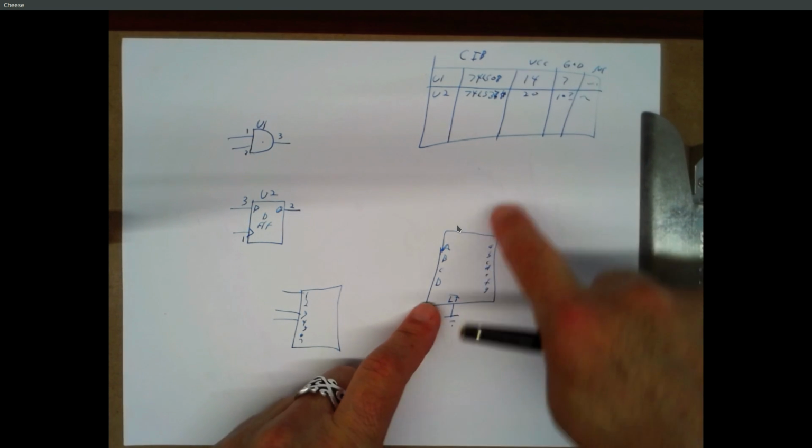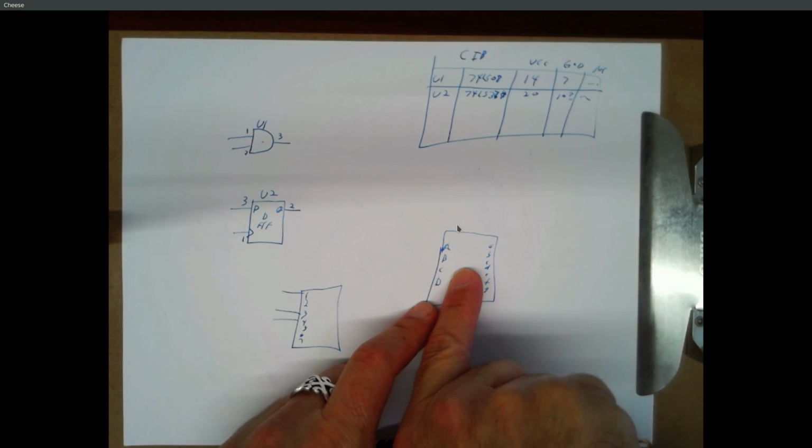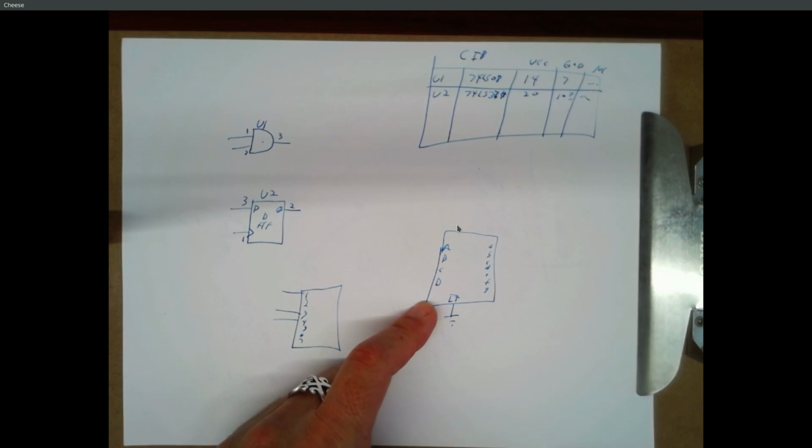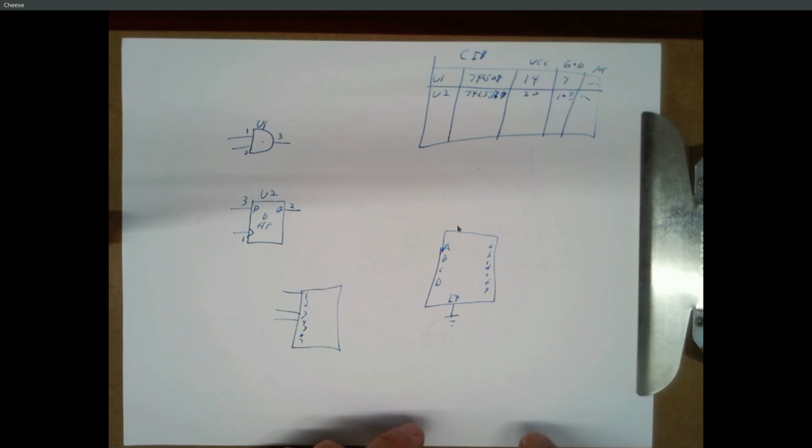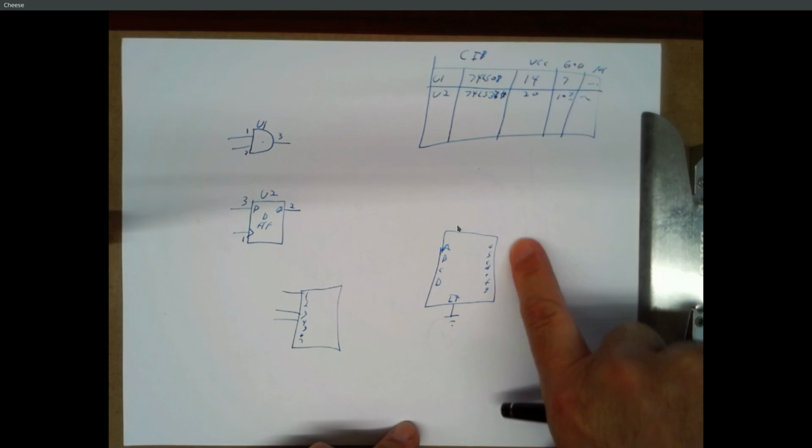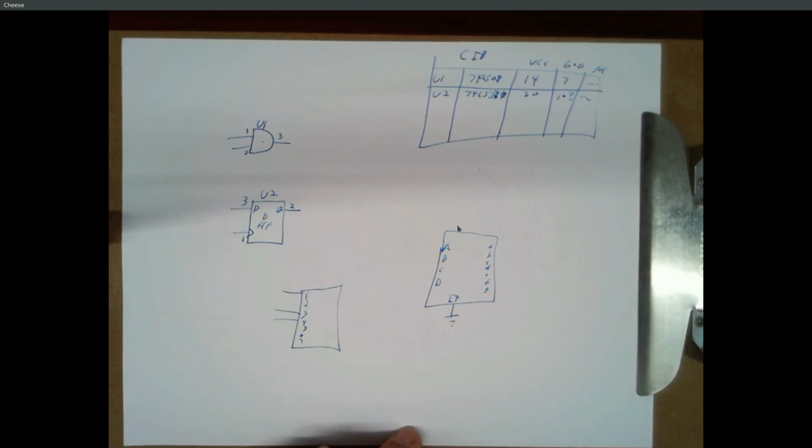If you know from looking up here, this is a 74LS47, and you look that up, it's like, oh yeah, 7-segment decoder. Okay, so those are the 4-bit values, and these are the segment outputs. So just labeling your blocks in a way that matches the specification makes it a little more usable to someone who's looking at the circuit.